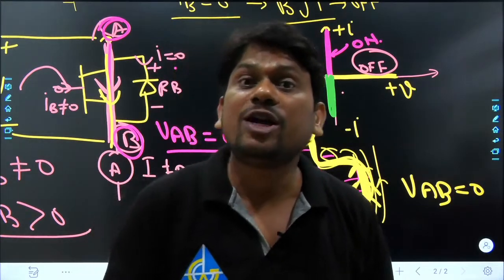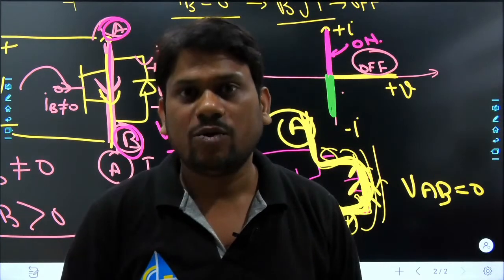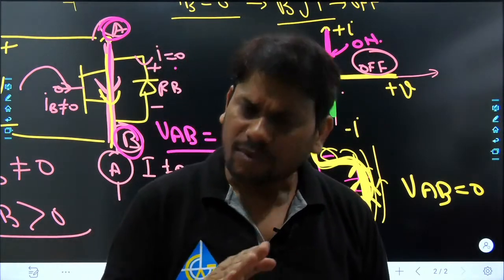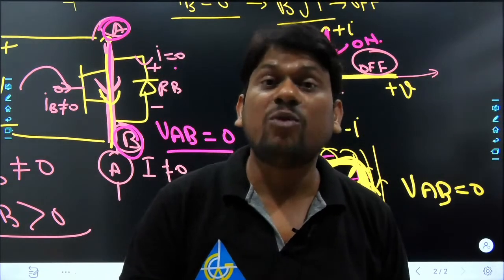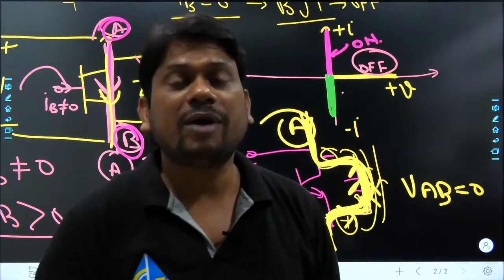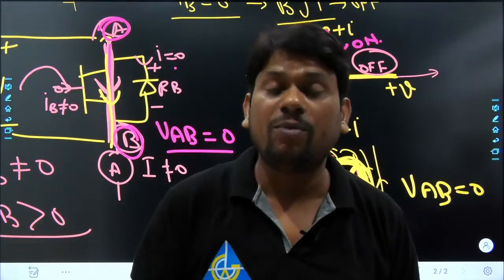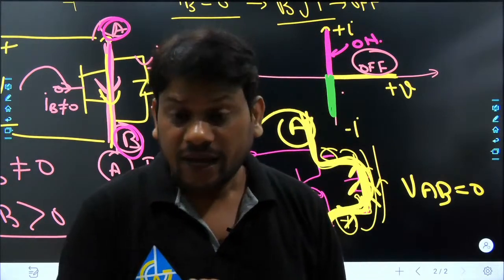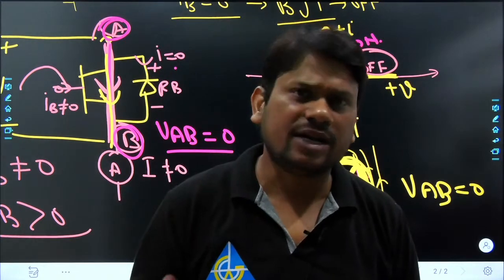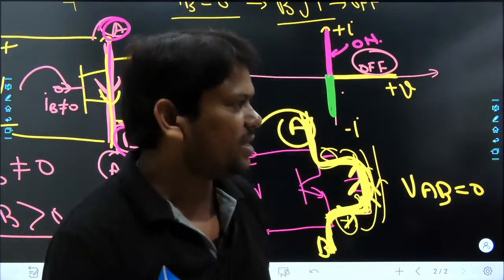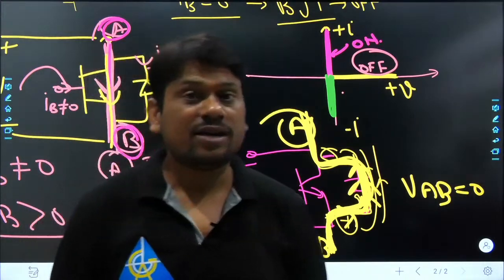So whenever we require current in load or anywhere in both directions, we cannot use single BJT. We cannot use single diode. So we can use the BJT and diode in anti-parallel. So that's why this switch module is somewhat better than our other devices at this moment, meaning diode or BJT, in terms of application. Now, how we can control switching losses and conduction losses, we will discuss sometime later. Yeah, very nice. So now tell me, all the points are clear to everyone?